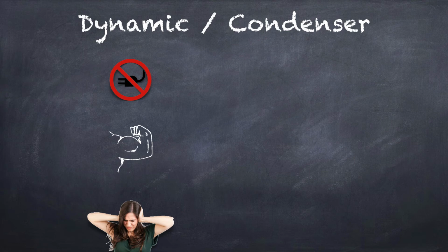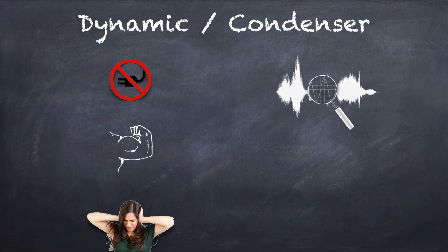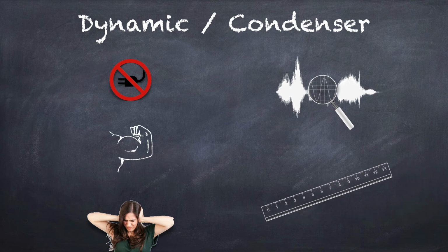The condenser microphones have the advantage of having a lighter membrane. This means they need less energy to be moved. This results in a much better sensitivity and a better precision. In terms of sound, we will be able to record quiet sounds and have a better quality in high frequencies. Also, condenser microphones can be constructed smaller. So, if you are designing a cell phone, for example, you will obviously choose this kind of microphones.